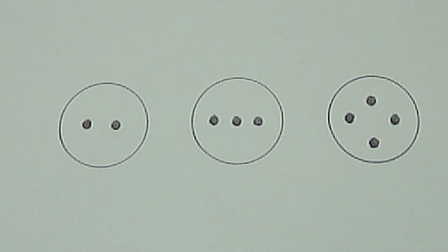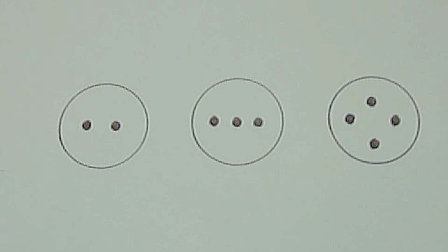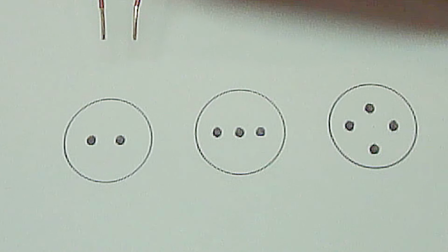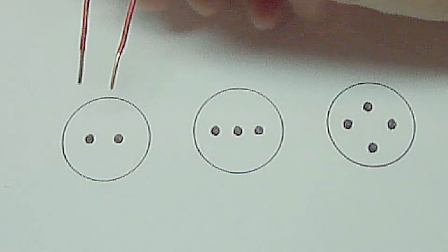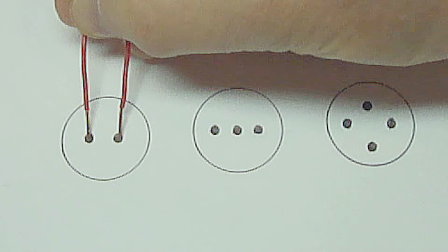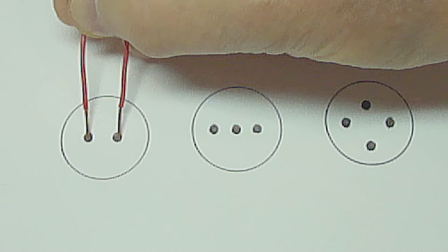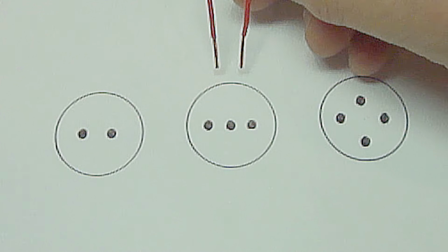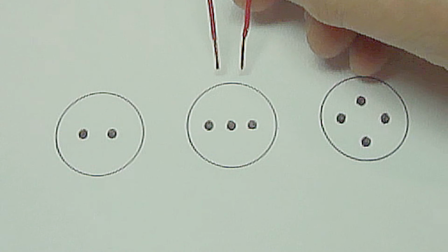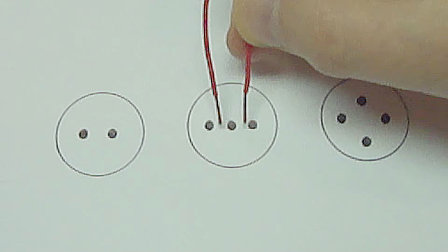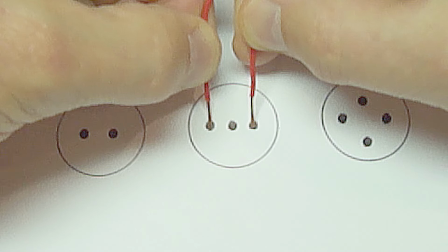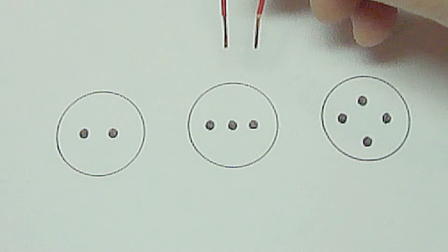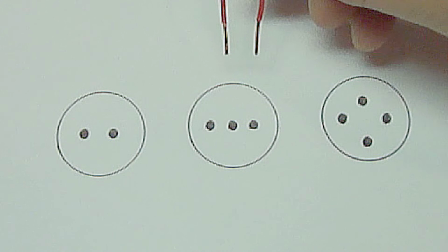For demonstration purposes, I'll first show how to perform a bypass test on this drawing, and then I'll do an actual test. If you have two electrical contacts, then test the bypass wire ends on the two contacts. This is now correctly bypassed. If you have three electrical contacts, then test the bypass wire ends here, here, and here. One of these combinations will be the correct bypass.